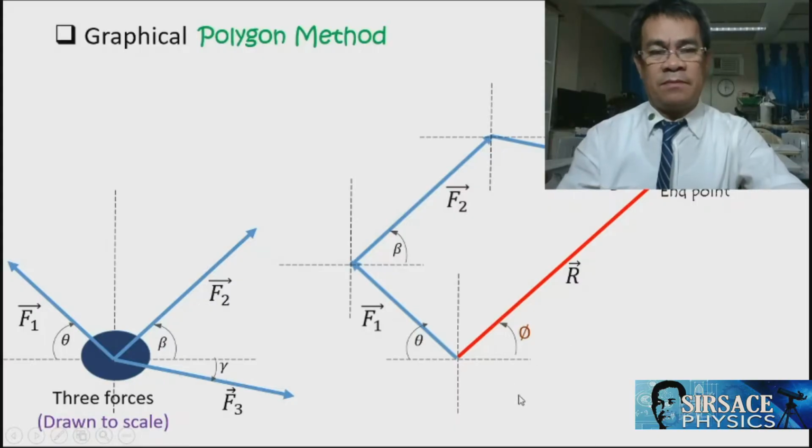That's it. Now, take note that we constructed a polygon. We started with F1, F2, F3. You can rearrange this. It is not necessary to follow the order. There is no such order basis. You can do anything as long as you are constructing an equal vector.